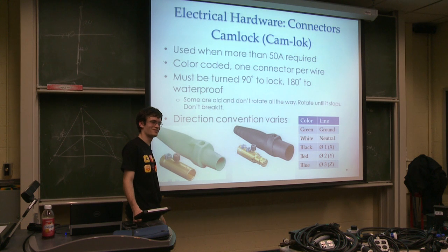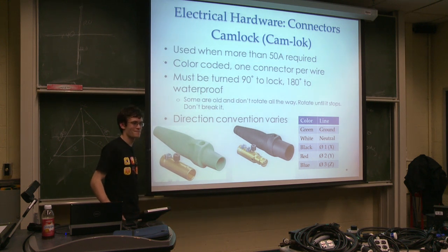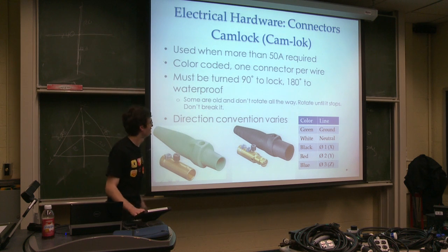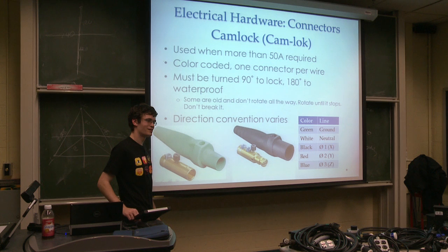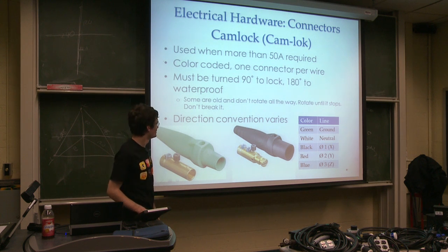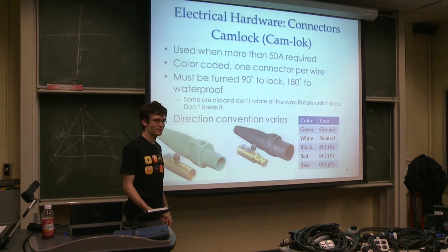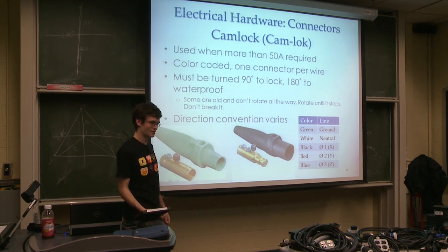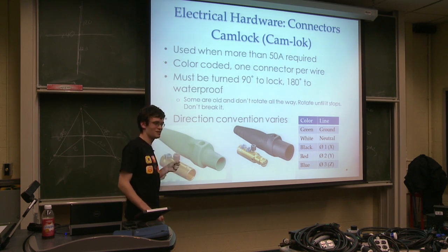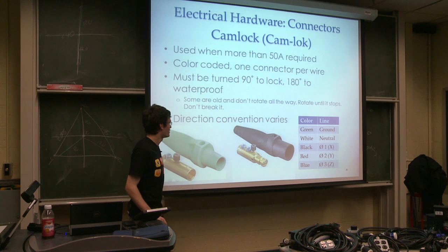Tom, if you want to share that story again. That we lifted the end of a generator with one by accident. Yep. Was it only 1 or 5 of them? It was probably one taking most of the strain. Okay. Also, Tech owns a 15-inch pipe wrench for getting these things off when they stick to PDs, which they do. So don't tighten them until you break them. Tighten them until they're secure, and they won't get yanked out accidentally.